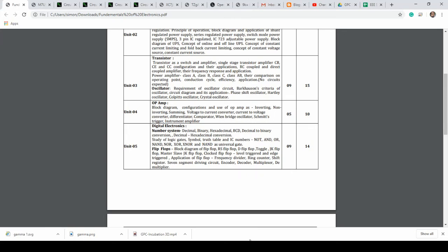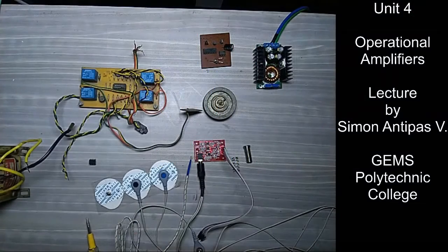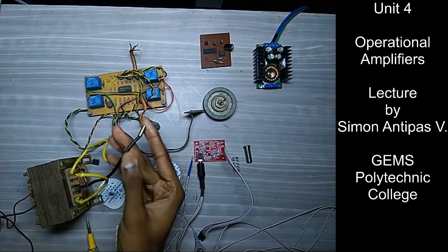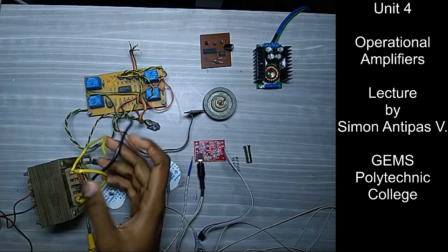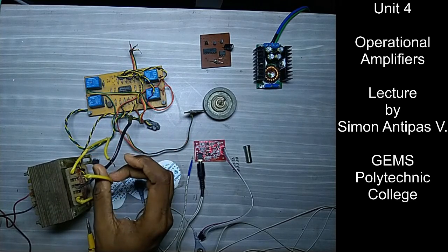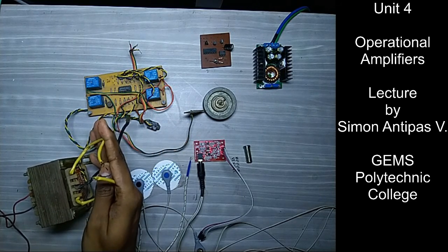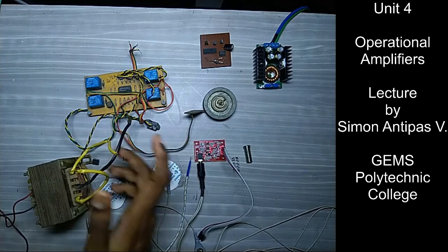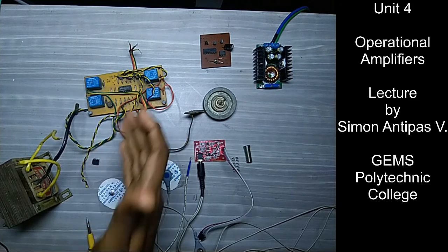For example, let's look at a power supply that I could typically use with an operation amplifier. In this case, I have a transformer. You've seen this earlier. It's a center tap transformer. In other words, this black wire is my ground. I could have plus 12 and minus 12. If I rectify this and I have dual power supplies, I would have a 0, plus 12 and minus 12 as a DC power supply being fed after rectification to my circuitry.